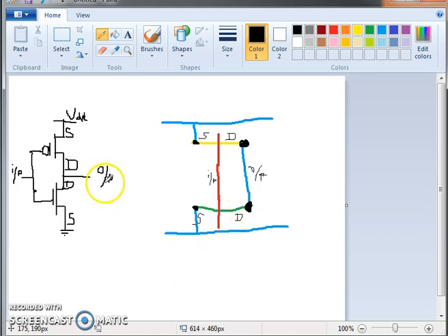Again, I'll repeat how you start drawing a stick diagram. First, you should have a circuit with you. Mention which is the VDD, VSS, input and output nodes, and mention which is the source and the drain terminal of all the transistors. Then start with drawing VDD and VSS, then start arranging or placing the PMOS transistors and the NMOS transistors. Poly crossing diffusion is a transistor formation.